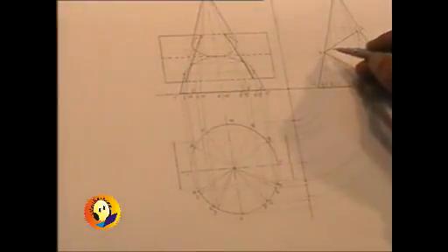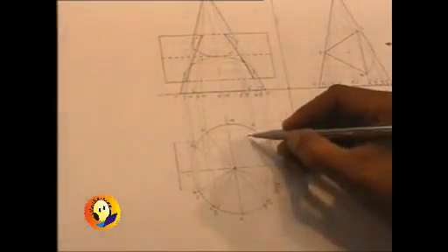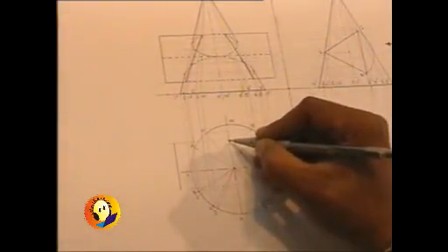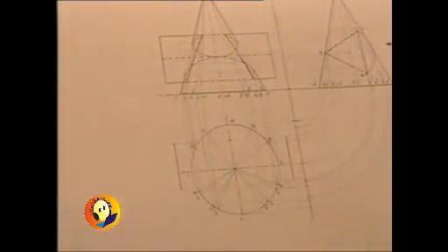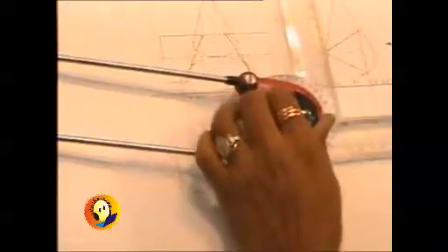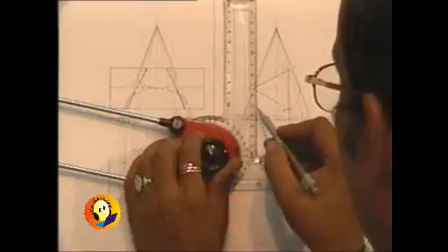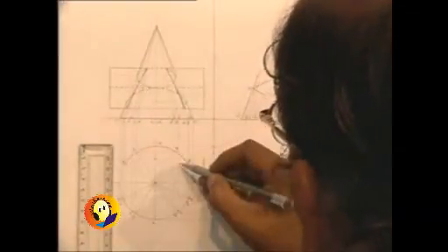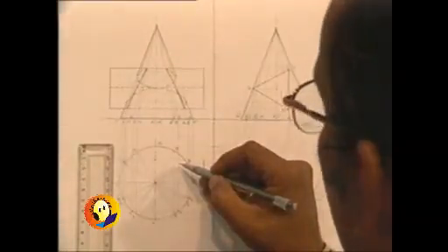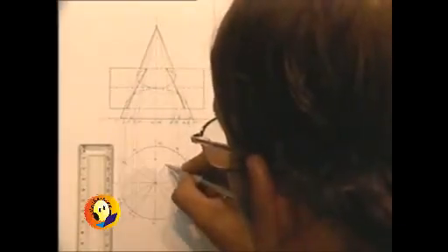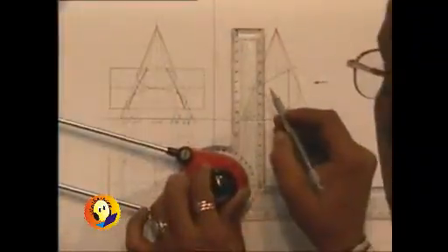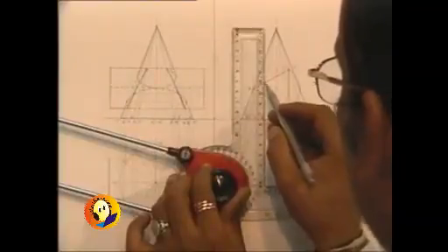Like we have point A, which lies on generator 10. This can be marked directly. Then if I am considering the top surface, I have a point on generator 8 and 12, and it is on this line. It is a point on generator 9 and 11, so it can be marked on 9 and 11. Then generator 8 and 12 is cut at this point.